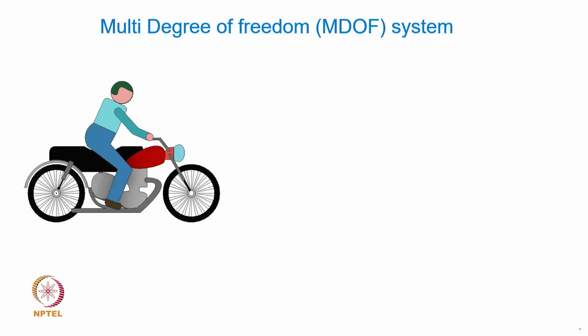So, I am bringing back again the physical system like a motorbike here, wherein we have earlier modeled it like a simple single degree of freedom system, where the stiffness of the suspension was found to be an equivalent one considering both the suspensions, and the chassis mass and the rider mass was lumped like a single mass having only 1 degree of freedom. That is how we started the whole analysis process of a system like this.